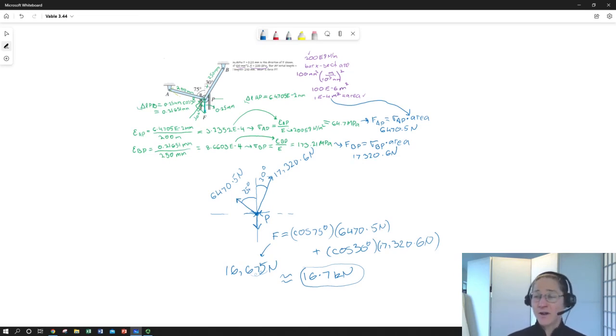So that's an example of how we can work back and forth from a measured displacement and known characteristics of materials and cross sections and original part dimensions to getting forces. We could have worked this problem knowing basically any set of those values, so long as we had the same number of equations as unknowns, we could have solved for any one of them. And which ones you'll encounter basically depend on whether you're doing maybe an analysis or capability assessment of a known structure, or you're designing something to fit a known set of loads and constraints. So that's it for this example.